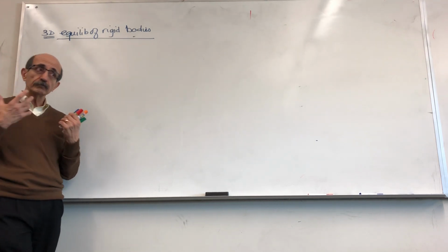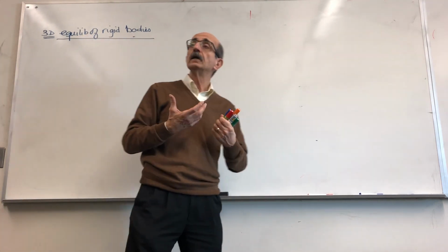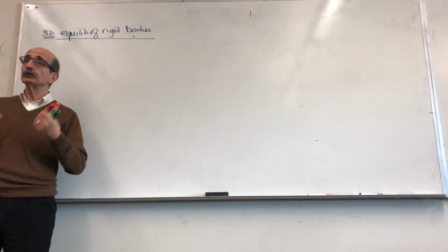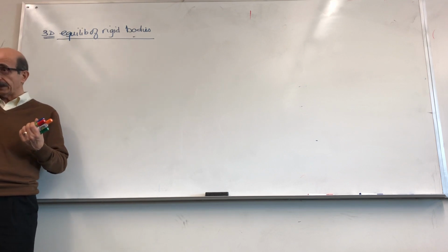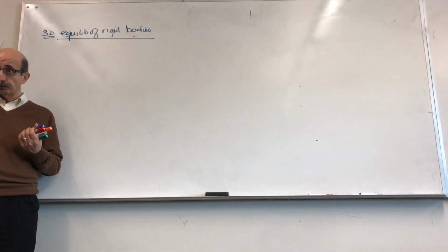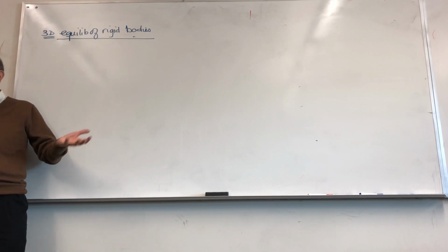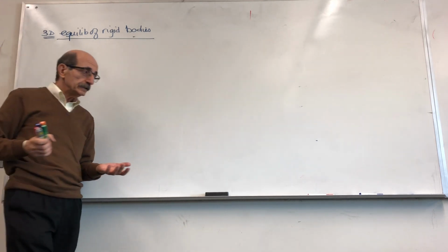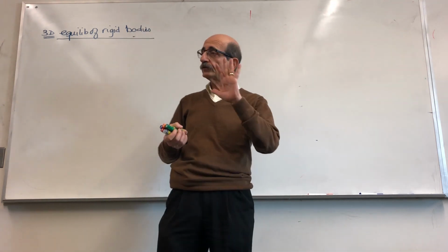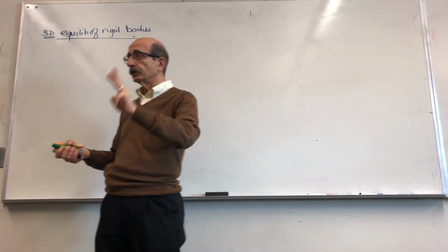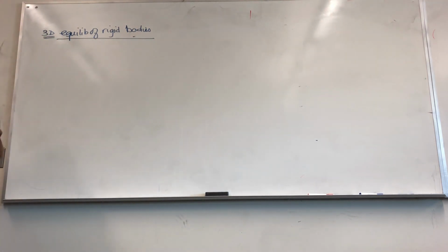So if you think of the number of potential directions of motion, there are 6. So you can have up to 6 unknowns at a support, right? Of course, that's a maximum number. So in general, you can have up to 6 unknowns in 3D versus only up to 3 unknowns in 2D.